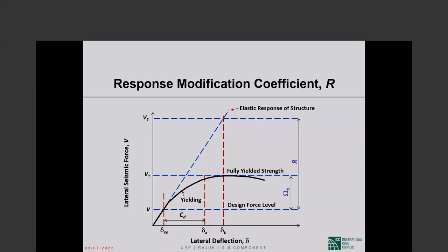If we want to figure out the largest bending moment that can be developed at this section, if the design earthquake were actually to hit, our estimate of that maximum moment would be omega sub 0 times the 100 foot kips negative. Okay?